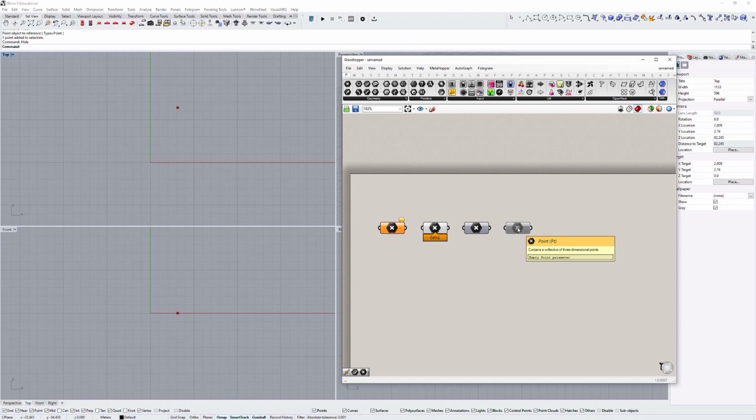And now you can see it more or less grayed out. When you hover your cursor over it, it tells you that the point parameter is empty once again. So these are kind of your four main preview options. You have a component that shows up orange, which means it's missing information or that there's an error. So you hover over the bubble or the balloon to see the message.